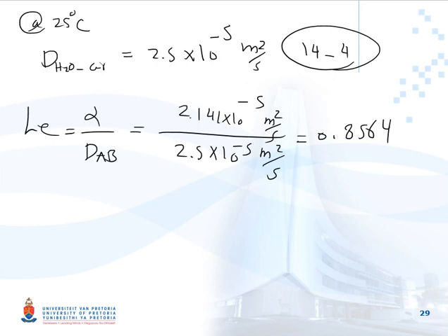So the air at the surface, we know that is saturated, and because of that the vapor pressure at the surface can be calculated simply as the saturation pressure of water at that surface temperature. So what is the surface temperature? We assume that the surface temperature is 20.